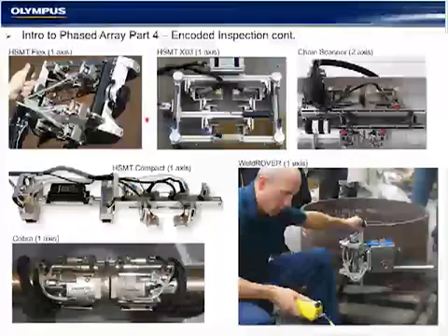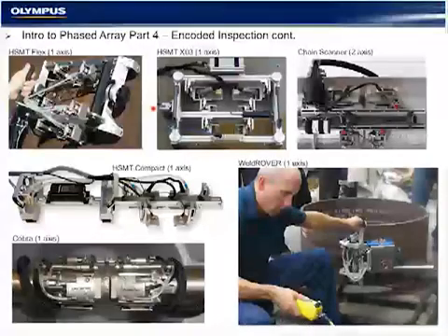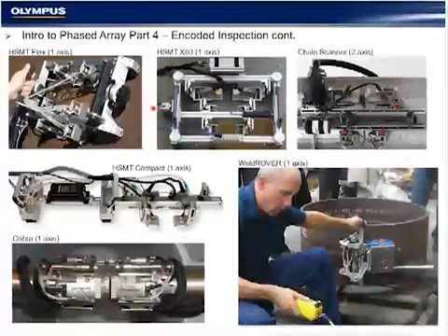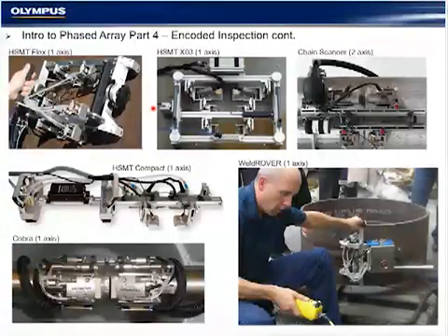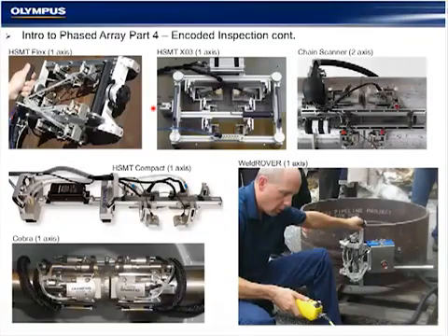In the encoder of the MX2 that you see here, it's a simple wheel that converts a clock trigger to distance. They're typically a quadrature type encoder, and they would have a resolution that tells the software that for every number of pulses received equals 1 millimeter or 1 inch. They can be calibrated, and in general, the resolution, once determined, if there's no damage to the scanner or wear, stays very accurate.